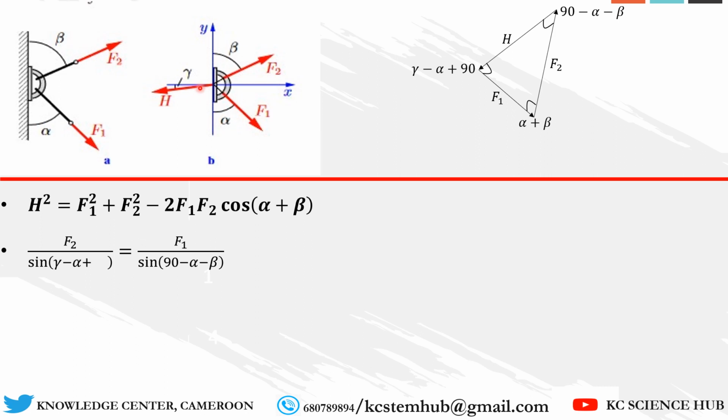But the next thing is you need to be able to define where forces act, like maybe gamma from the horizontal. So we need to look for gamma. How do you do that? Of course, you use the sine rule. So you get f2 over the sine of this angle, which is opposite, equals f1 over the sine of this angle, which is opposite.